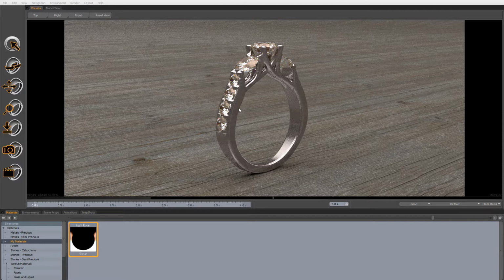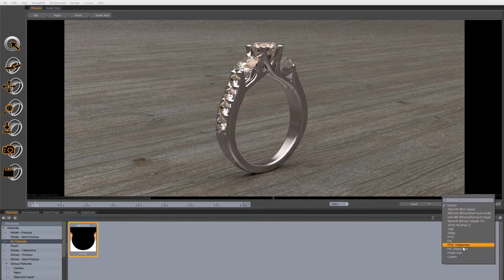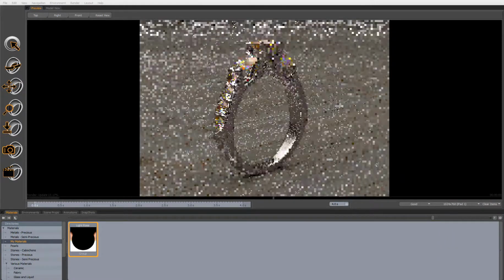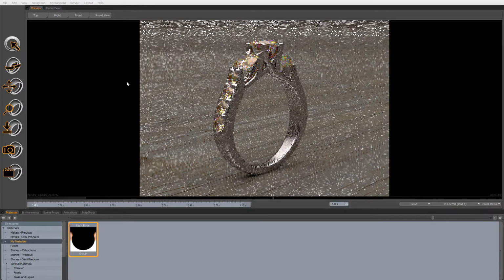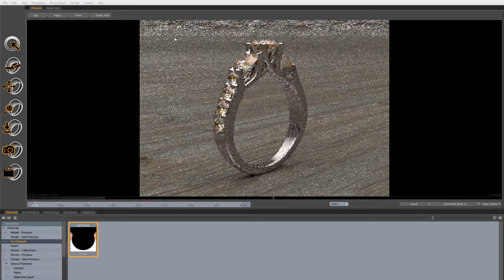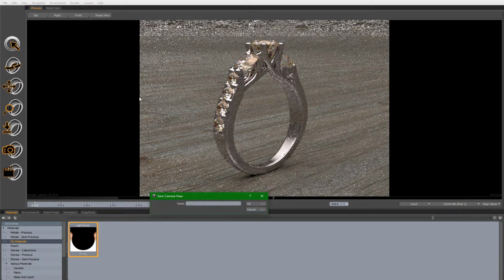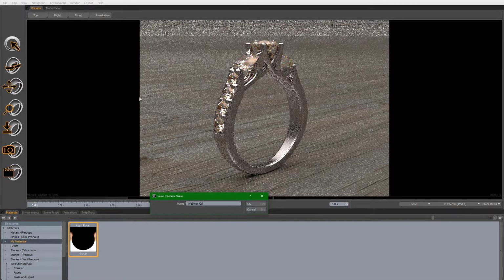Another of our biggest requested features for the new version was when you're rendering things out, and I like this camera view here. I'm designing this for my website, so I want all of my rings to be in the same position with the same resolution, the same settings. We go ahead and set our resolution. Okay, line up your scene, same controls that you have in 3DESIGN: zoom, rotate, and scale. And over here under view, we just simply say save camera snapshot. And I'll just call this webinar camera.